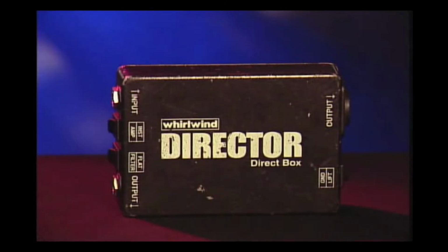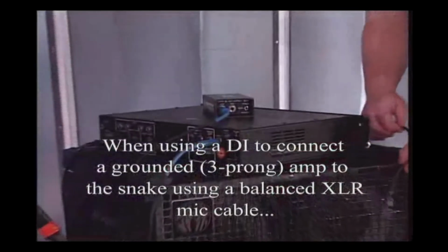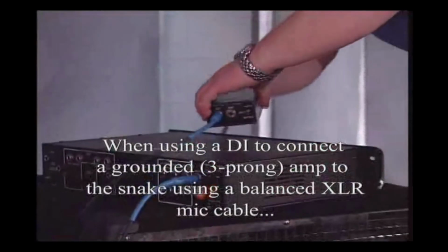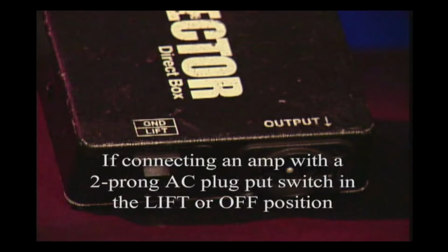Direct input boxes are another source of potential grounding problems. Generally, when a DI box is used to connect a grounded musical instrument amplifier to the snake using a balanced XLR type mic cable, the ground lift switch needs to be in the lift or off position. Such a switch is designed to disconnect pin 1 of the XLR connector on the unit. If the amplifier uses a 2-prong AC plug, leave the switch on the DI in the ground or on position.